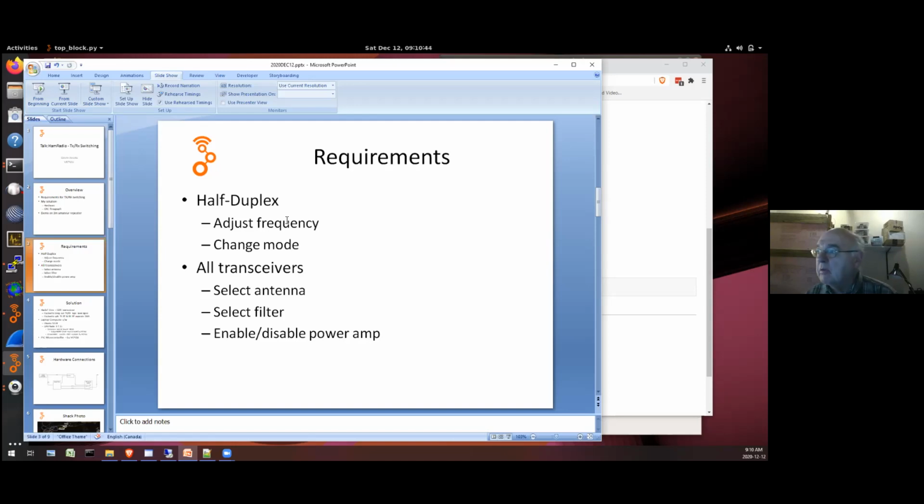You look inside those radios, they've probably got some sort of switch inside, an antenna control that switches between the circuitry for receive and transmit and turns on the power amp on transmit and so on. So that's all happening inside the transceiver that you have for amateur radio.